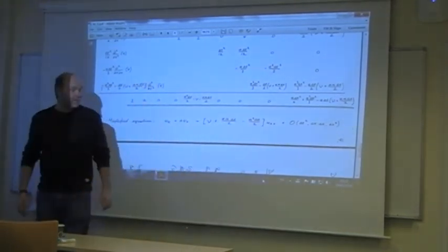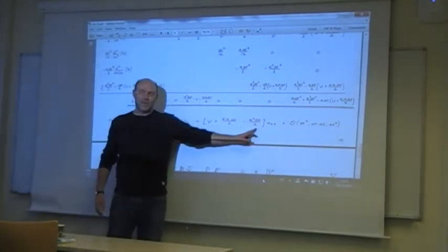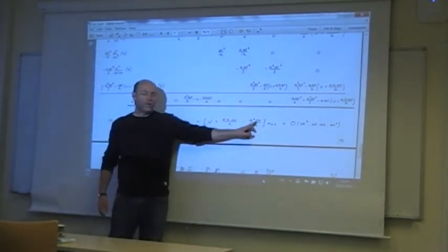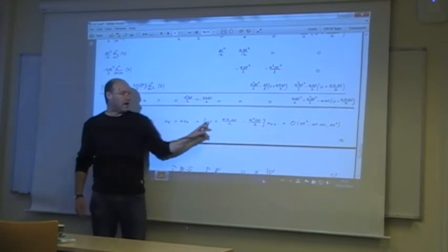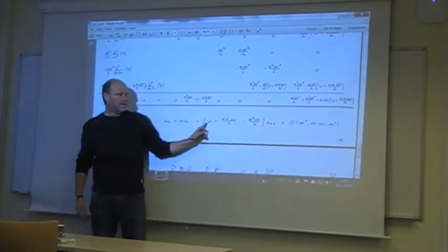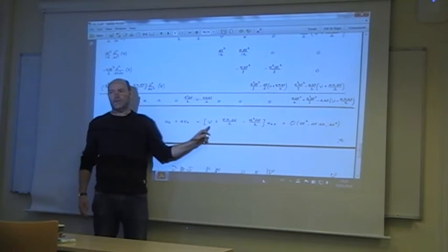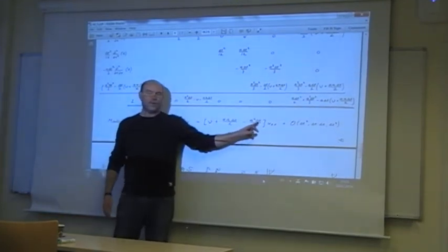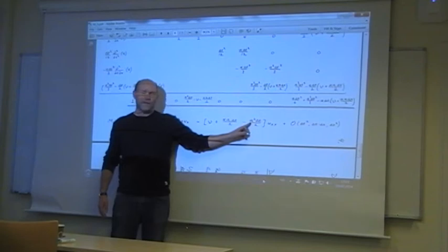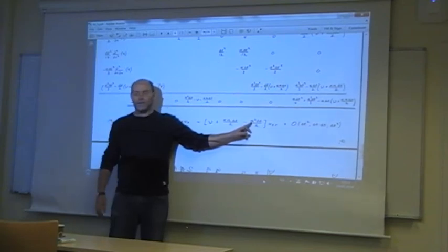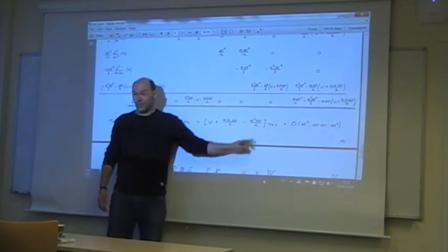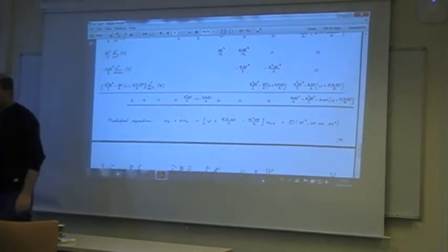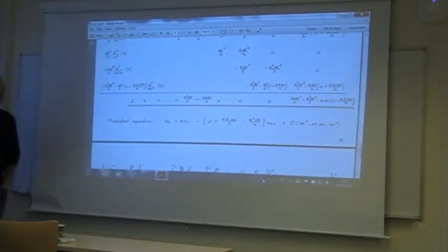And in practice, this can be very big. Of course, with a small enough delta t, you could survive and get the overall viscosity positive. But remember, for real fluids the viscosity is very, very small. Then this is going to be very, very small, and the a, the velocity in front of the convective term, can be big, and then it's squared. This can be a real pain, of course.